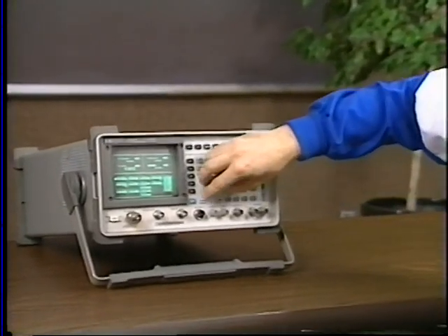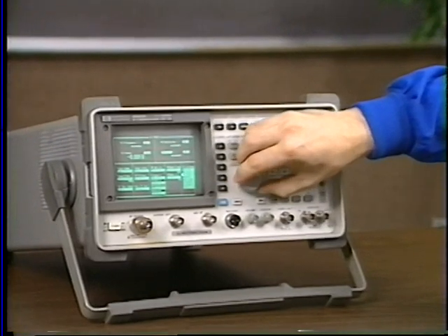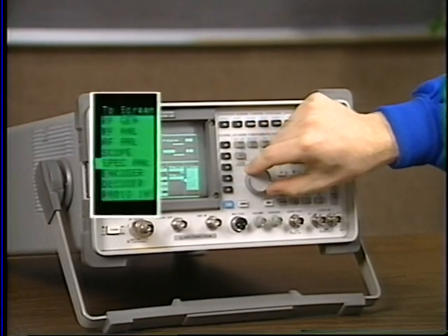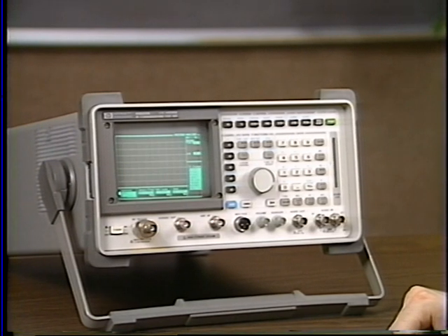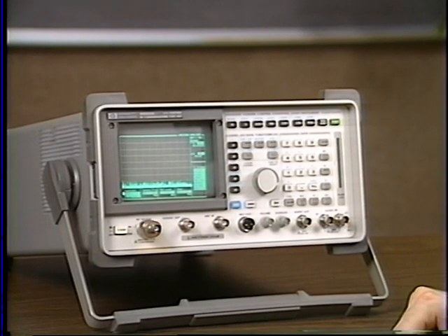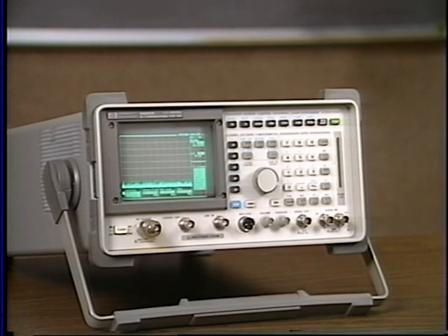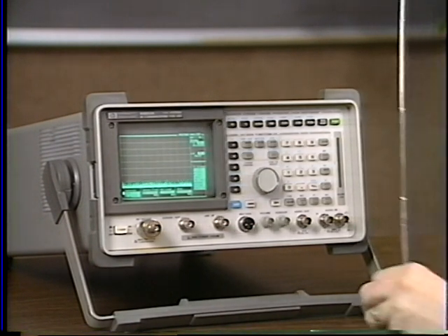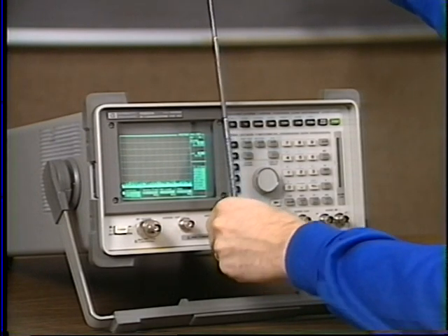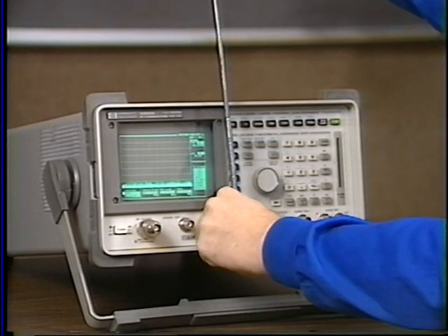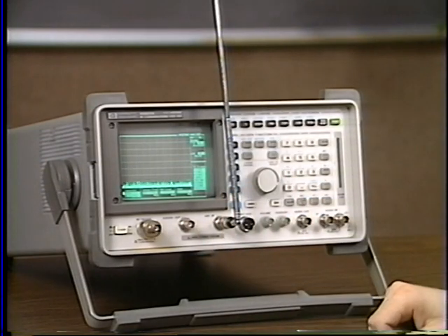To access the spectrum analyzer, position the cursor in front of that choice in the two screens area and press the knob. And the 8920 spectrum analyzer display will come up. Next, connect an antenna to your input port. We'll use the antenna input port, the high sensitivity antenna input port, for making our off-the-air measurement.